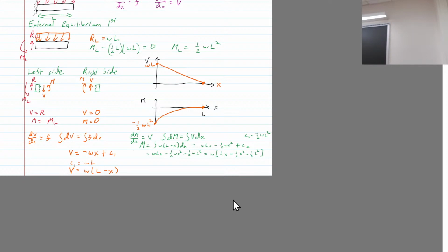Then Z. Here we do have a moment, and is it going to cause tension or compression? That's a tensile stress. PZ times A is the moment about the axis, and that will be a negative My over I, but it's going to be tensile. Can you go back to my diagram, because I want to make sure it's PZ times A. PZ is into the board. I'm doing the positive for now and applying negatives later.